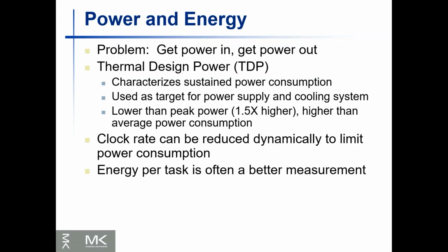So those are some of the problems. So how can we reduce this power consumption? Obviously by going to a different process node, reducing the clock rate, which also affects the performance, and also turning off components. So when you're not using your Wi-Fi, it will power down the Wi-Fi module. If you're not using Bluetooth, it will power down your Bluetooth module. So that's another technique to shut down components which you do not use.